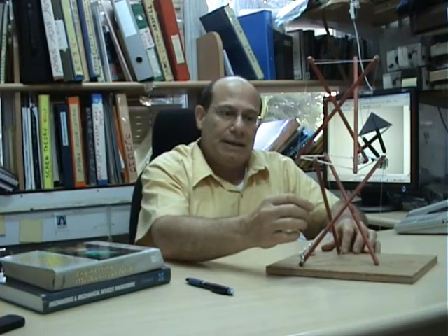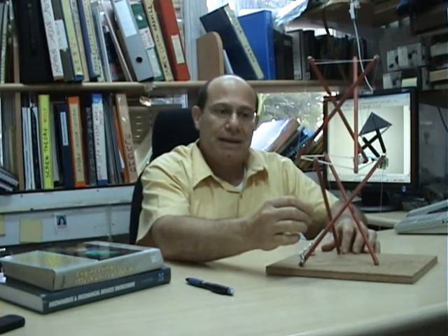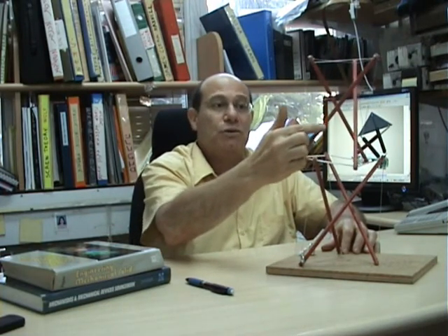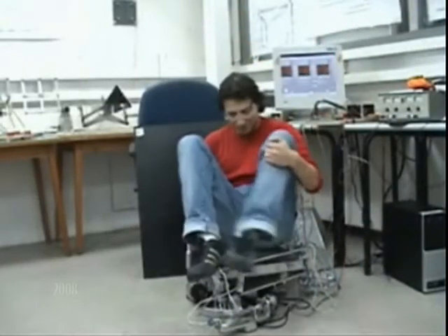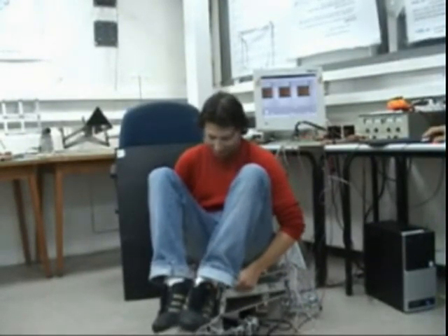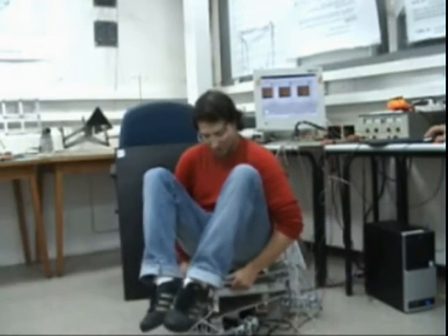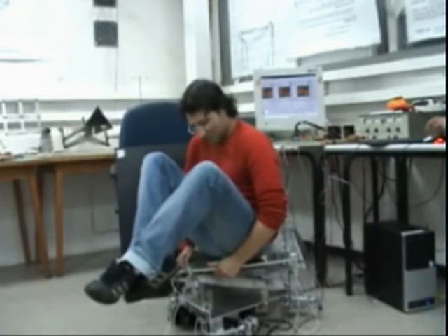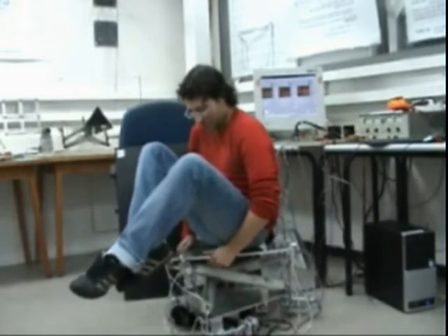In our device, we have two types of element, as in the human body. The cables sustain the tension. The struts sustain the compression forces. Equipped with 3 adjustable cables per floor and operated with a smart algorithm, load cells measure the tension in a fraction of a second and ensure the rigidity of the structure. We even succeeded to deploy the robot with a person on it.